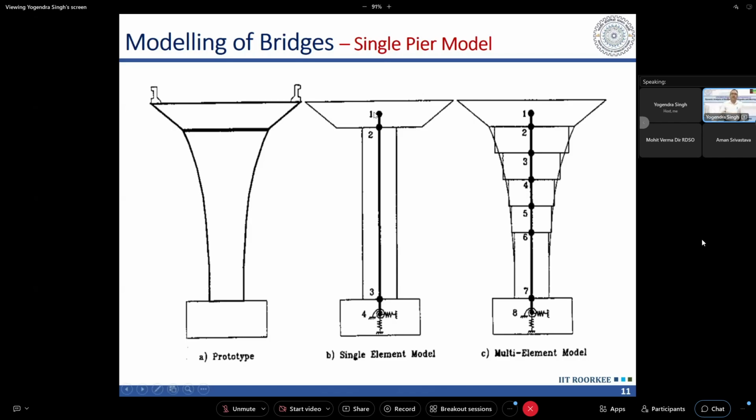If we have a normal simply supported bridge in which one end has fixed bearings and the other end has roller bearings, then in the longitudinal direction the whole mass of that bridge will be lumped to the pier to which it is connected in a rigid manner. And the other pier will be relieved of that mass.